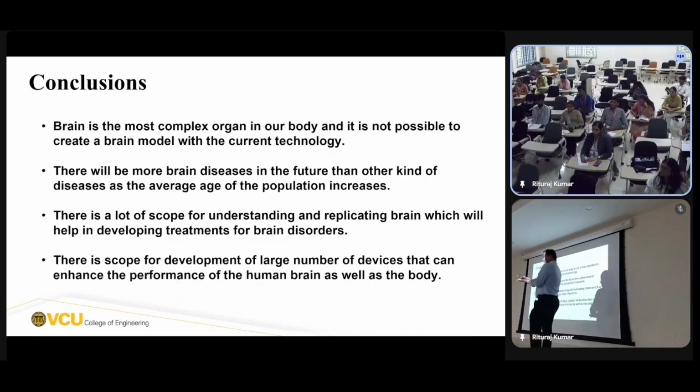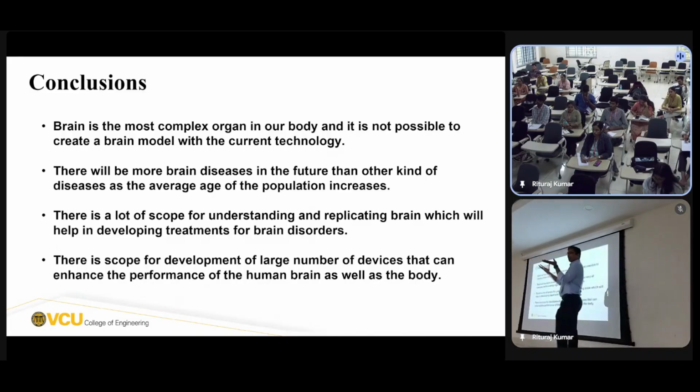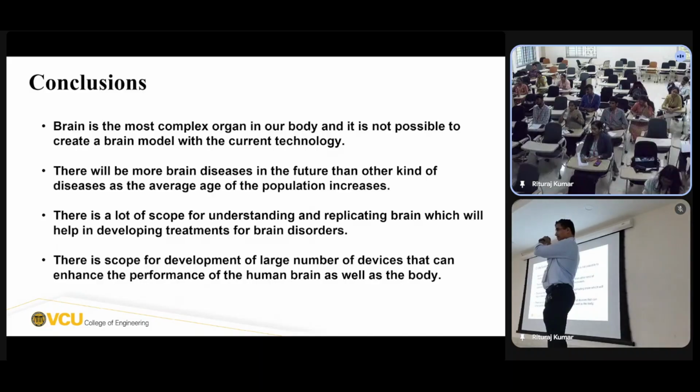So there is a piezoelectric at the bottom. On top, you have a magnetostrictive material. Apply magnetic field, magnetostrictive material oscillates, that creates piezoelectric oscillations. If piezoelectric material oscillates, what happens? Generates a voltage, right? And that voltage can be used. So if you have a nanoparticle and you have a core shell where the core is magnetostrictive material and shell is piezoelectric material, okay?